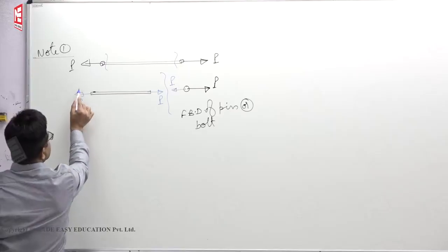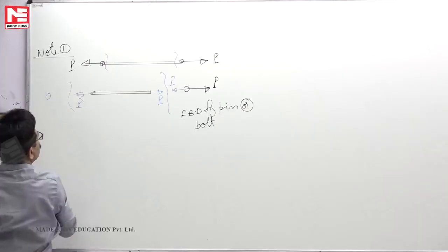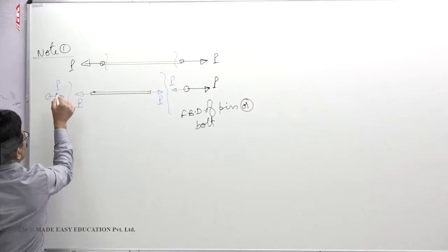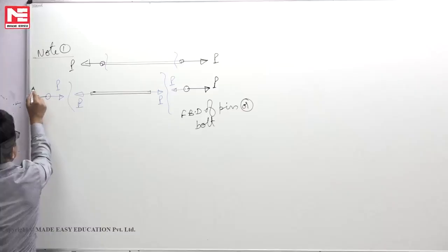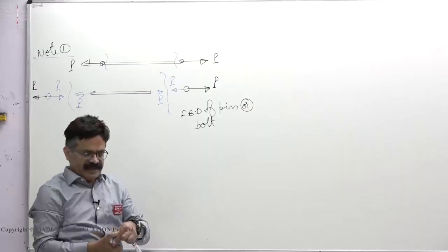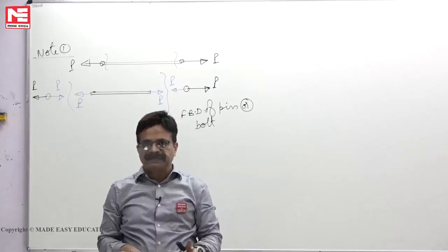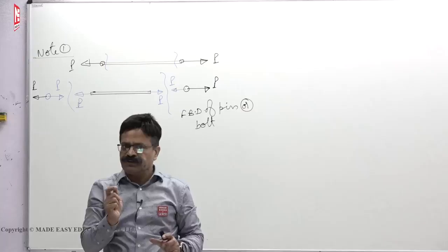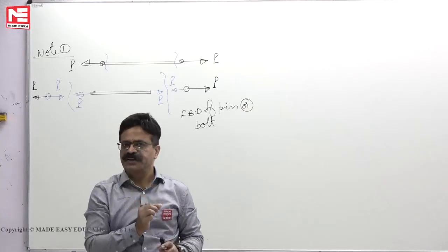Now this force is exerted by the pin. If I draw the free body diagram of the pin, the member will exert a force P on the pin like this. To balance this P, all the other three or four members will pull it like this. Now individually each member is in equilibrium. Remember one thing: if a big structure is in equilibrium, any small piece you pluck out of it, each piece of the structure must be in equilibrium like this.